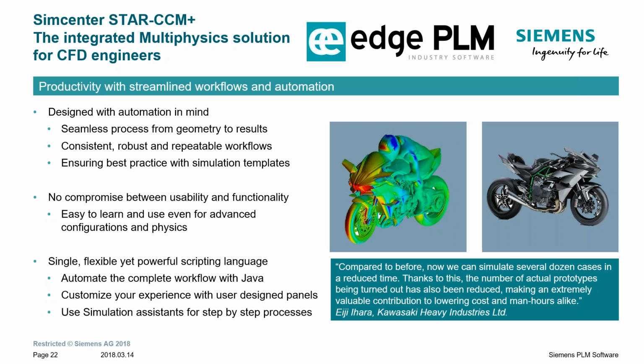You can also create and modify computer-aided design models of your geometry using a fully parametric 3D feature-based modeler. You can establish a bi-directional link between StarCCM and your CAD product or your lifecycle management tool software so that geometry updates are automatically represented in your simulation. You can repair and defeature imported CAD geometry using industry-leading surface wrapping and repair tools, automatically creating a closed surface in as much detail as necessary to ensure the fidelity of your results.